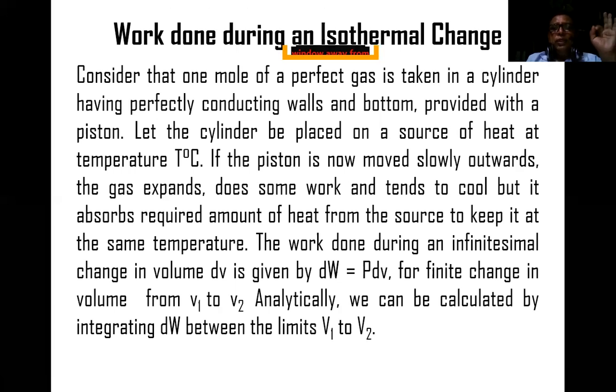The work done during an infinitely small change in volume dV is dW is equal to PdV. For a finite change in volume from V1 to V2, analytically we can calculate by integrating dW between the limits V1 to V2.